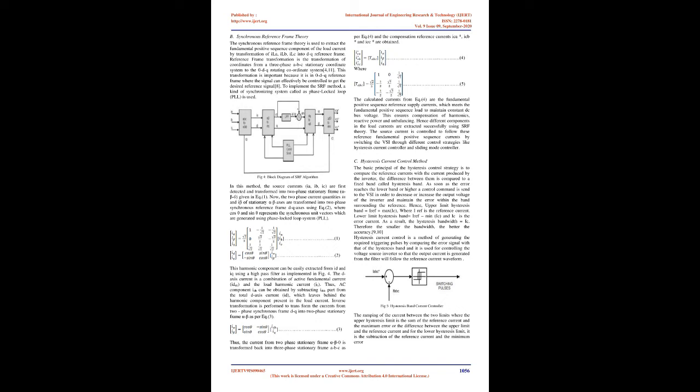Control techniques. A. Instantaneous real and reactive power theory. In 1983, Akagi et al. proposed the generalized theory of the instantaneous reactive power in three-phase circuits, also known as instantaneous power theory, or PQ theory. The PQ theory consists of an algebraic transformation, the Clarke transformation, of the three-phase voltages and currents in the abc coordinates to the αβ0 coordinates, followed by the calculation of the PQ theory instantaneous power components.